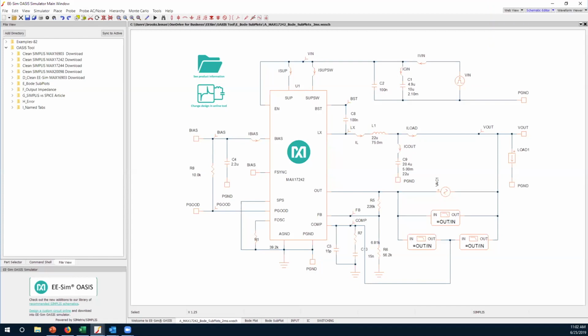He then asks, is it possible to simulate power controllers with external MOSFETs, and how to change or use different models of MOSFETs? We can use external MOSFETs, but the MOSFET models for SIMPLIS are simple representations. It's difficult to import a SPICE model into SIMPLIS.